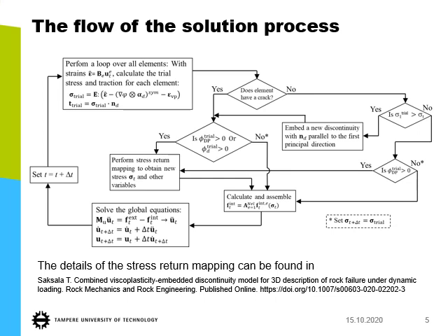And again, increase the time and go further. Start again. But if these loading functions are not violated, if the element has a crack and there are no violations, the stress state is elastic, and we calculate the internal force vector and go to the global solution again. Okay, if the element does have a crack, that was that. If the element doesn't have a crack, then we go to check the first principal stress.